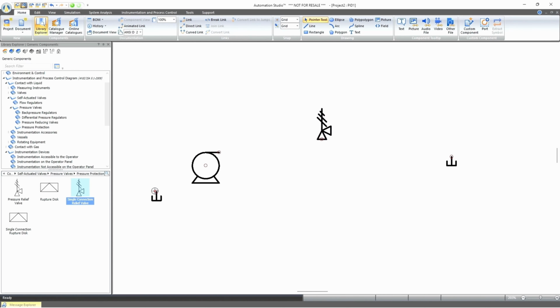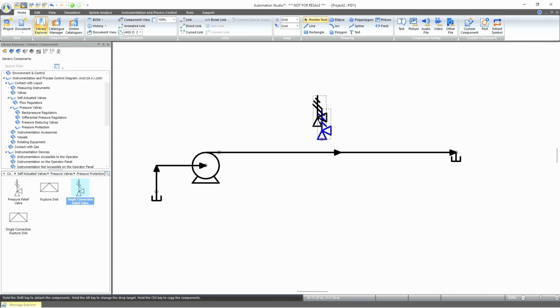You will notice, and this I wanted to bring your attention to, how the construction of the system is a little bit different than you would expect. This is part of the requirements of the ISA standard. Main flow lines need to depict, for example, the flow direction in the sheet itself. So in our case, in addition mode, you will be able to see these kind of lines.